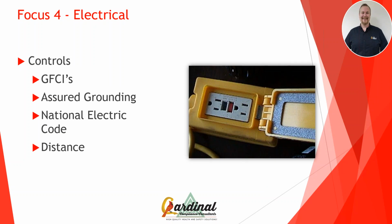Now, there's a lot of controls we can put in place, and some of these are very basic in construction. If you've never heard of a GFCI, that's just a plug you'll see in your kitchen, in your bathroom, anywhere that we have water sources. And basically what that does is it measures how much energy is flowing into the system. Then it compares it to how much energy is moving out. And when it notices a difference, that GFCI realizes, hey, we're leaking electricity somewhere, something's happened. So it shuts off the flow of power within a split second. So that doesn't stop you from getting a shock. What that does is it minimizes the shock, the duration of the shock.